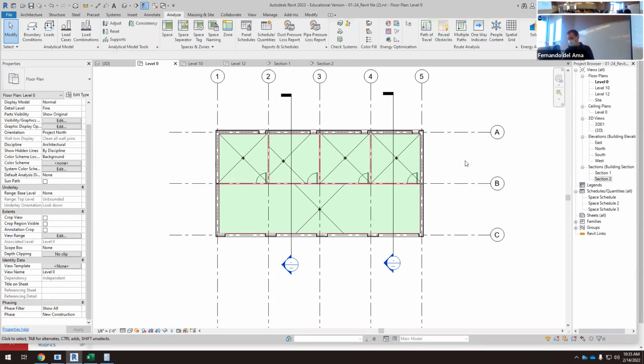Okay. Yep. I'm not seeing the spaces for the 2nd and 4th room. I think I missed the step for like allowing them. Move the section. No. Right. Move it here. Oh. Yes, select it, move it, and now open section 1 again. So you have to check different sections, and if it doesn't show up, it's probably because the space is too low. So that's important. We create the space, we have to check that the space is there.